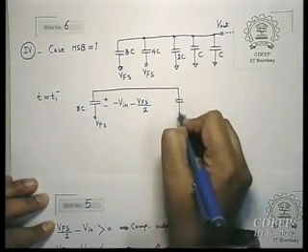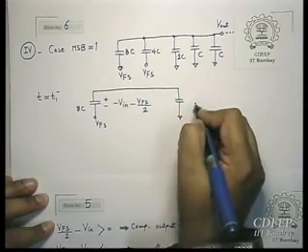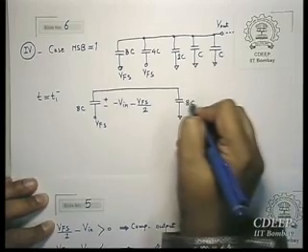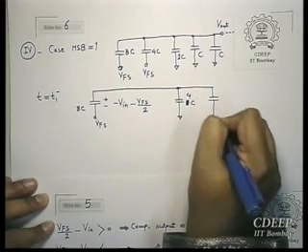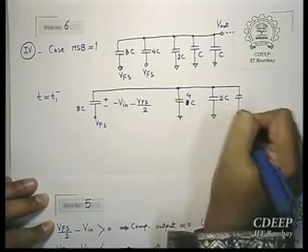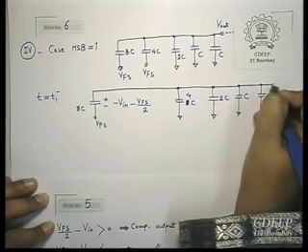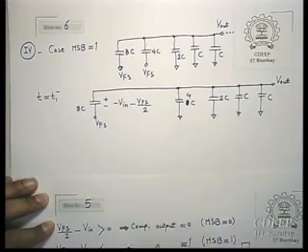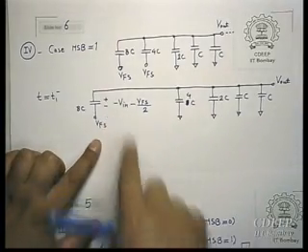And other capacitors were connected to ground. And the total value was 8C, right? So no, let me separate them, because 4C will get connected to V full scale now. So 2C. So this V full scale, therefore you had V full scale by 2.